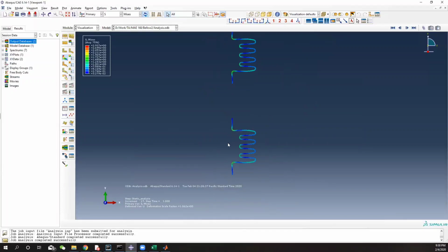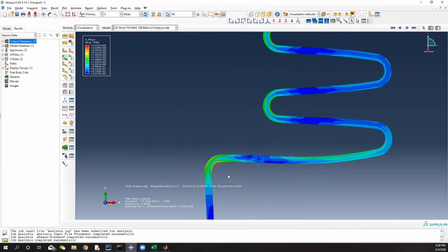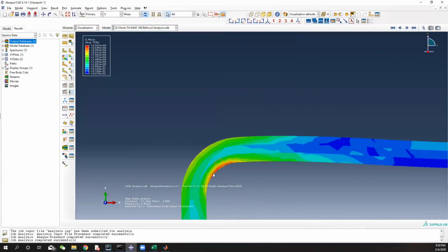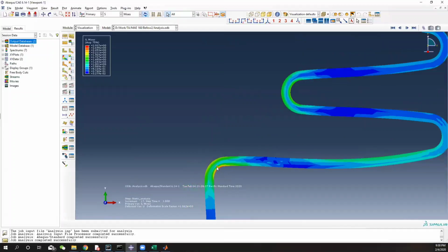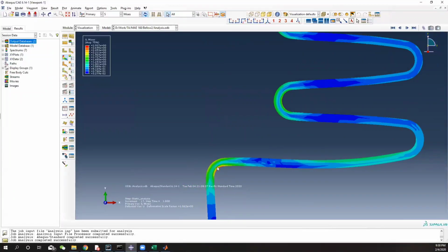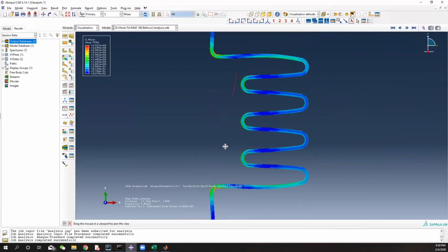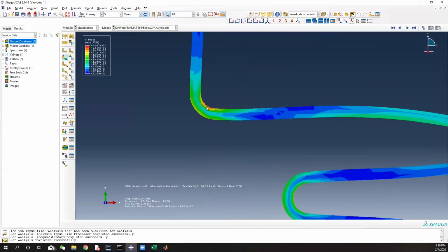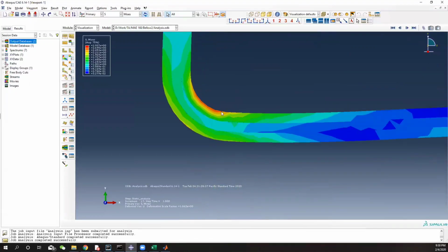And you can see at the final stage, remember previously our conclusion was that with stress concentration, the maximum stress will be on the lower and bottom and top of the fillet. Now we are more clear that it should be located at the inner side of the fillet.